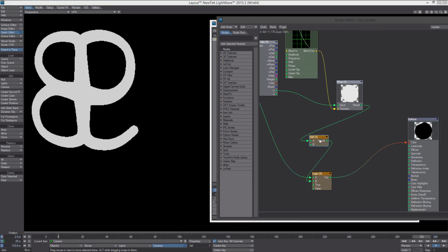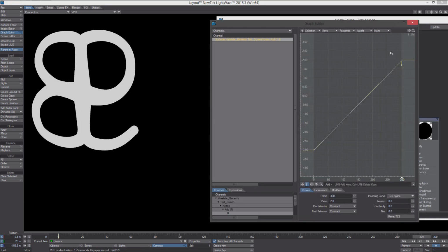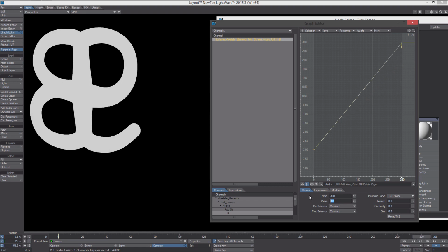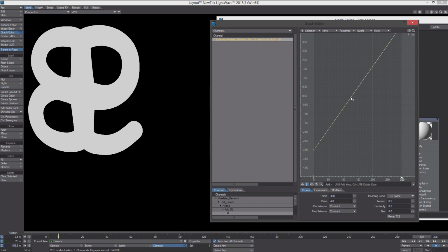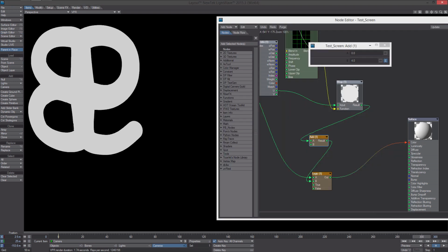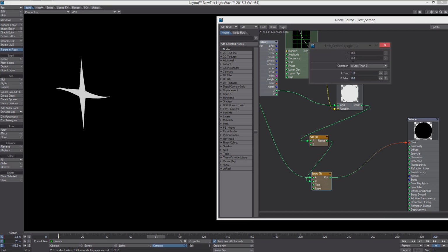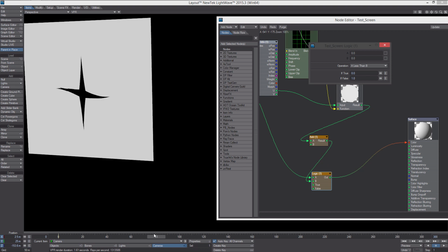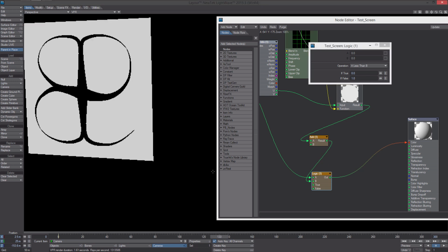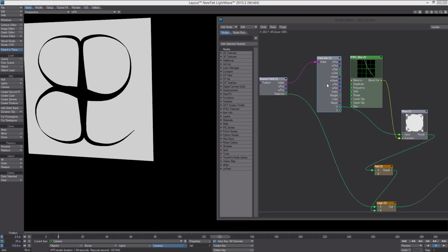So that's pretty much how we're going to reveal this tessellation. So now I'm just changing the value up to 4 because it needs to encompass the whole BP, plus even a little more, because those instances are a little bit bigger even. So now I'm just inverting it so that it's black in the middle, because for a clip map that's what you want it to use.